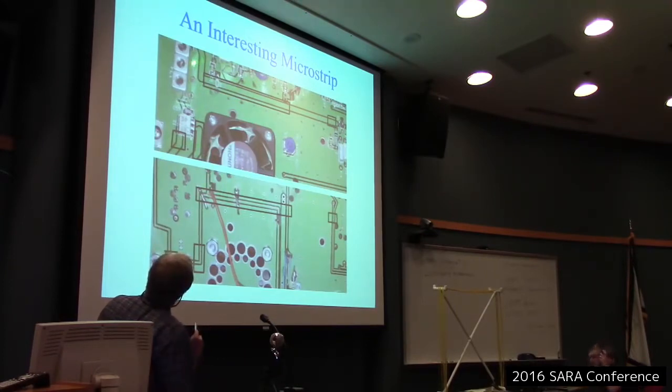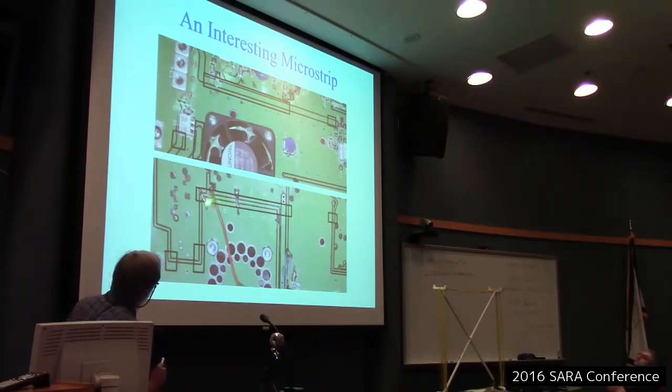So you can see there's my microstrip running signal from a receiver circuit up to a mixer area on a receiver. The receiver has this part of the microstrip right here, and it's got a power trace running right under it. You can see here my first attempts at an improved repair, where I cut the power free of the trace in every place where it was underneath there and ran little ground straps across here. That improved things, but not as much as I wanted.